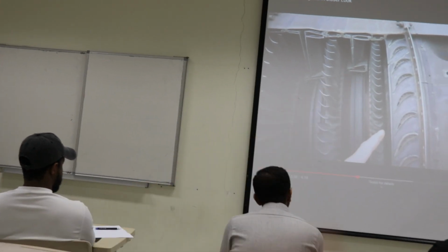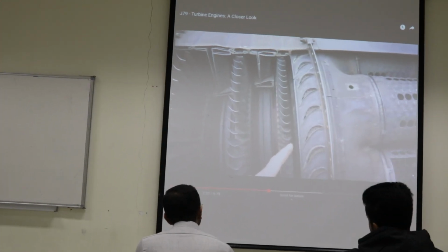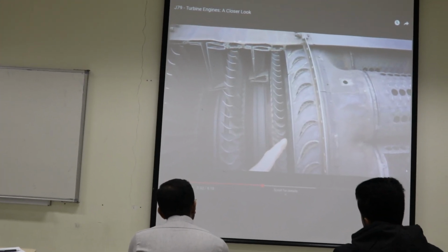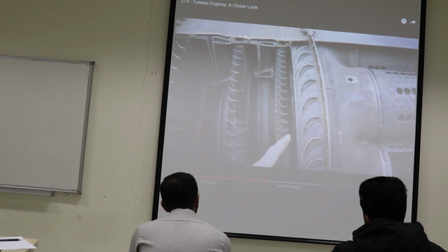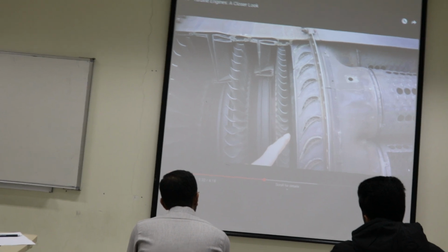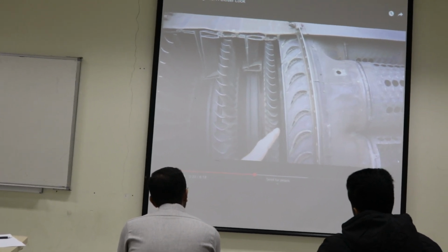So you see, guys, the first row, the fixed blades, what are those? The fixed blade takes the shape of a nozzle, so the flow will be going between the plates, leaving the combustion chamber, okay? And then it will be accelerated to high speed.